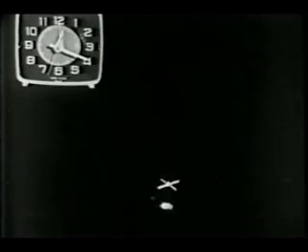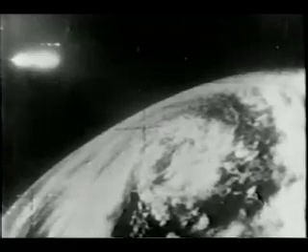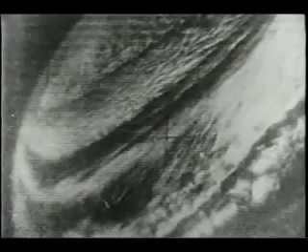In our large tank, before we started the flow, the fluid had a very small vorticity in inertial space due to the turning of the Earth. When the plug was pulled, the vertical fluid thread on the axis was enormously lengthened, and the vorticity in inertial space was strengthened proportionately, finally to the point where we could see it in the reference frame of the Earth. These photographs of the Earth's cloud cover, taken from the satellite Tyros, show that similar events occur in the Earth's atmosphere on a grand scale.